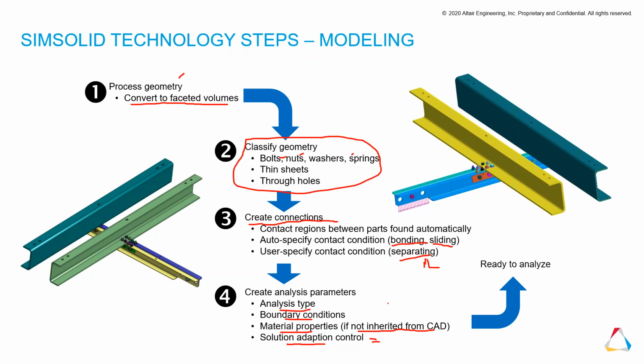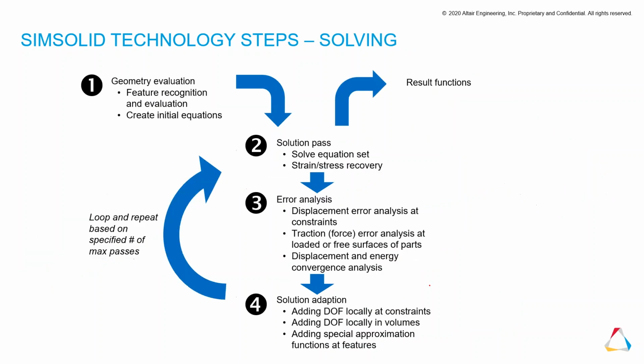So if, let's say, you define steel in your CATIA and you read in the file, we can read the material name steel, and if we can find the exact name in SimSolid, we will apply that material to that part, right? Otherwise, you have to define it manually yourself. Okay, so at the moment we can read JT, we can read from NX, from CATIA, and from SolidWorks, right? So those materials are carried over. Otherwise, you need to create your own materials later on in SimSolid.